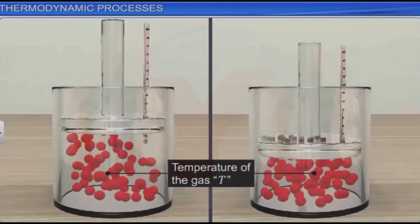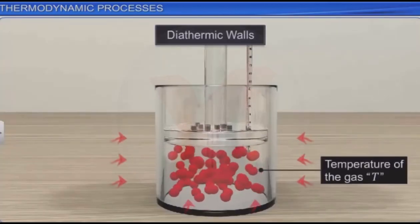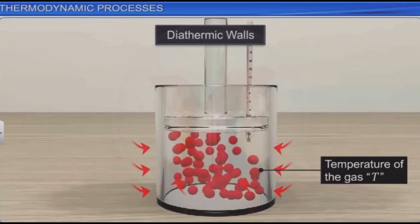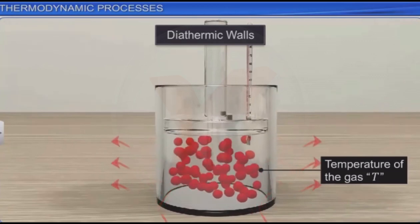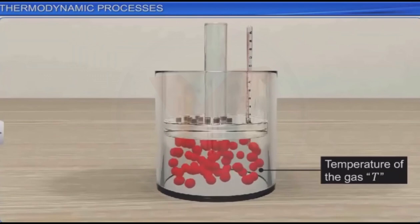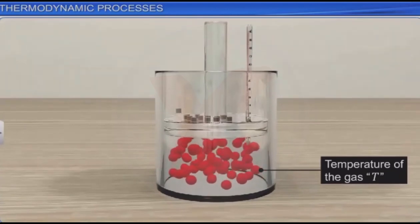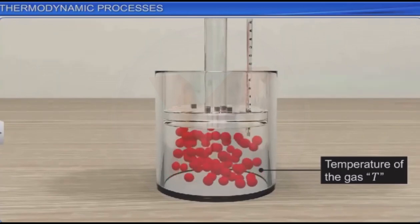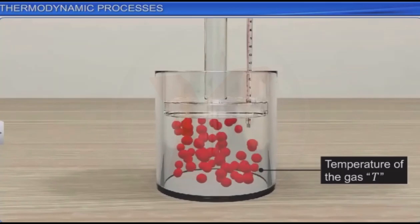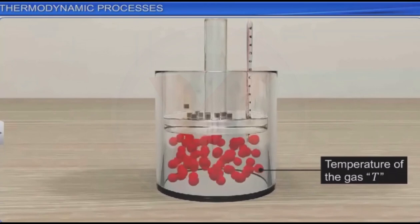To maintain a constant temperature, the gas absorbs heat energy from the surroundings during expansion and releases heat to the surroundings during contraction. Since the internal energy of an ideal gas depends only on the absolute temperature of the gas, there will be no change in the internal energy of an ideal gas in any isothermal process. This means a change in internal energy delta U is equal to 0.